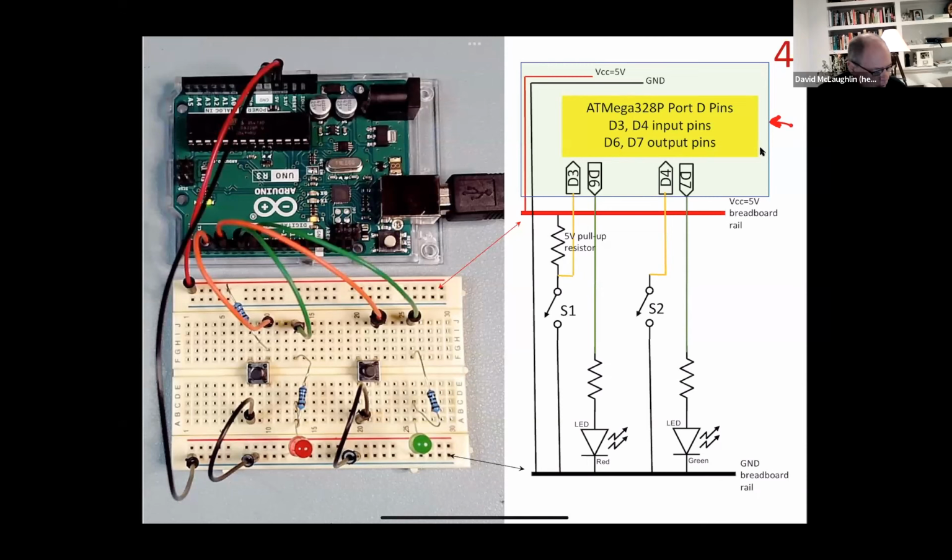But within one of these breadboards, if we look at where that red wire connects, we've got a red wire going from 5 volts on the Arduino, right? And then it comes to this top horizontal row. And then within the breadboard, connected all the way down this line, there's actually a piece of metal underneath. So it provides connection all the way down that line. You call that one of the power rails or the voltage rails on the breadboard.